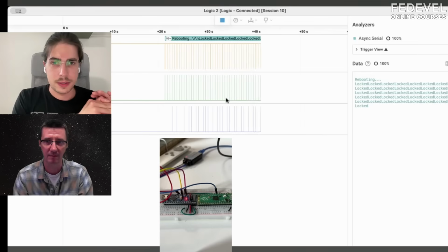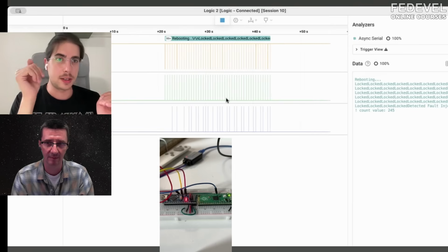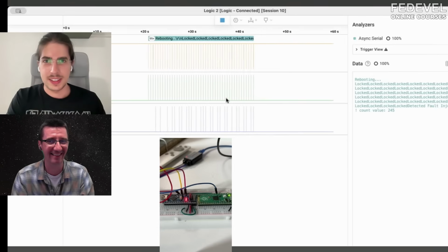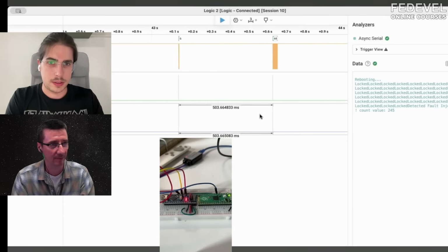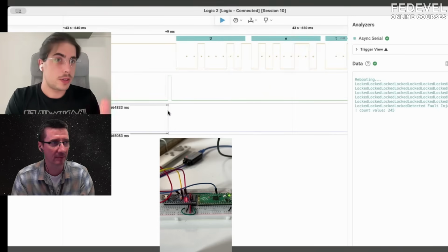I only have this addition register, and it means if I glitch the add instruction, then I get 245, like here maybe. But if I glitch the jump instruction, then I could exit the loop way earlier and get something like 50. Yeah, this is all stuff that you want to figure out as a hardware security engineer to know what you're glitching.